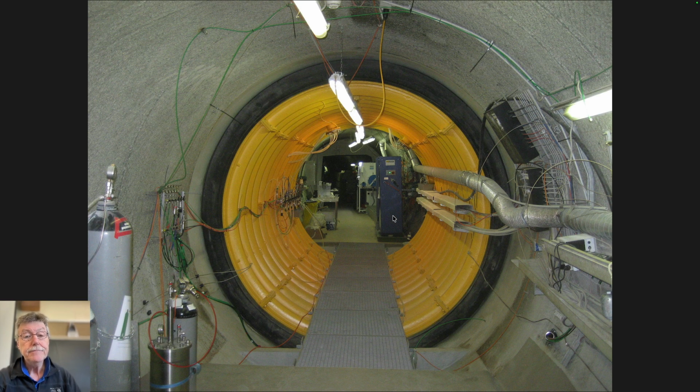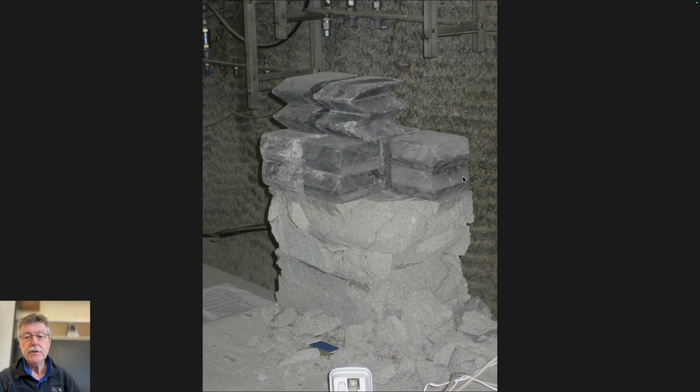A super big packer. We talked about straddle packers straddling in a borehole to isolate a central portion. This is a packer that straddles a fault. A fault is a kind of broken zone within the rock, which is present coming down vertically. It's the full length of this width, which is maybe 4 meters, perhaps 15 feet or so. This is a steel casing with a neoprene packer on the outside, which is inflated against the wall to be able to do experiments in this big fault to see what the hydrogeology of this natural feature is.